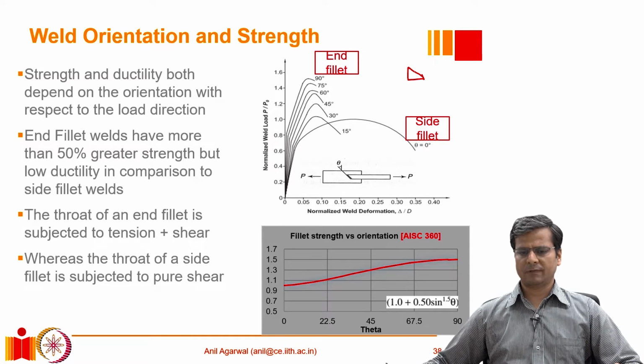So, for example, a fillet weld typically can be approximated to a triangle, right? A structure of triangular shape. This is one plate to which it is welded, and let's say this is another plate to which it is welded. I am creating some gap in between so that we can appreciate the difference. Now, let's say the bottom plate is restrained at this location and the top plate is being pulled. If that is the situation, imagine how the force would get transferred from this plate to this plate. And for the sake of symmetry, let's put another weld on the other side so that there are no questions about the possibility of opening of the root. Let's say this is the system.